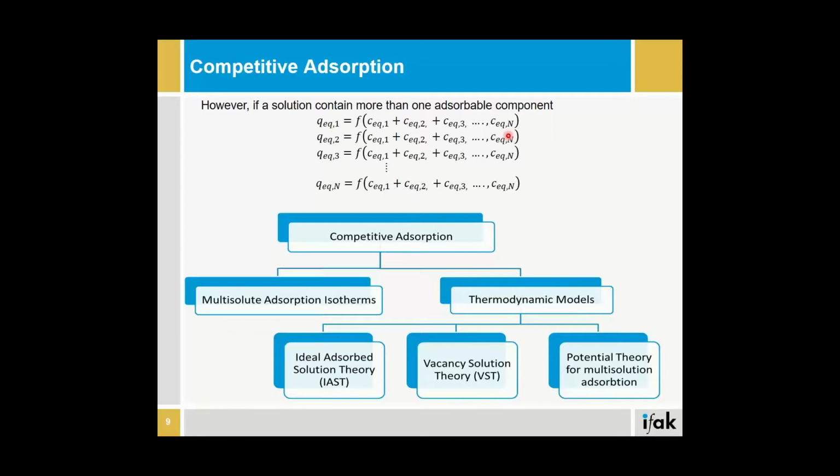And for that reason, the previously mentioned isotherms are not suitable by themselves. I need something a bit more sophisticated for competitive adsorption. So I either use multi-solute adsorption isotherms, which I will not be discussing here, but they're basically extensions of the Freundlich isotherm and other isotherms. And there are what are called the thermodynamic models.